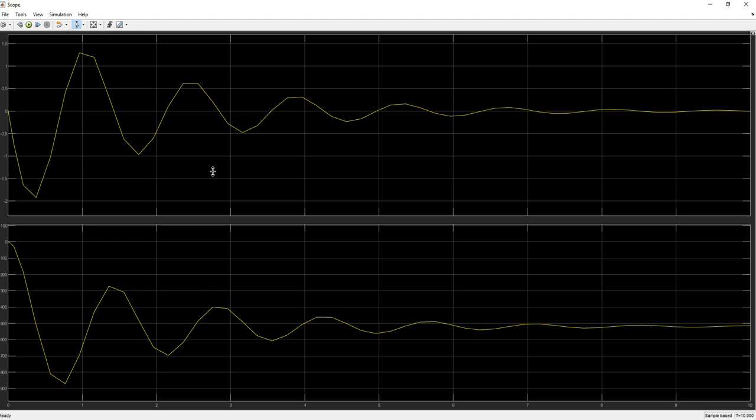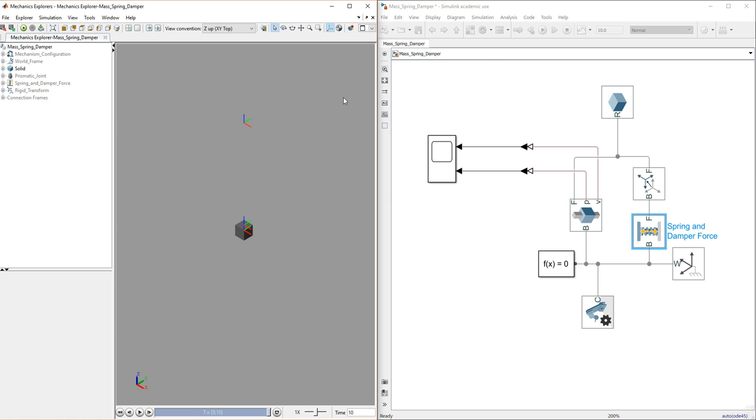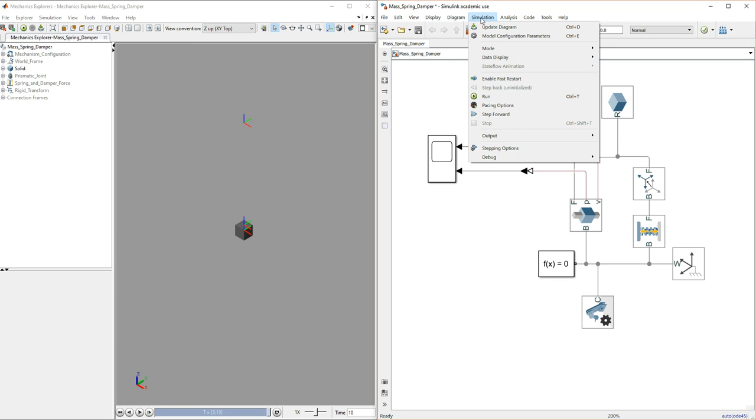The relative tolerance that we're using on our solver is basically making it unsolvable at this point. It's trying to block the points together. Basically, it's plotting these points and then just drawing a line. What we need to do is tighten up that tolerance on the solver. So I'll drop that, and let's tighten that up. Then let's hit it with a force, and then I think that's it.